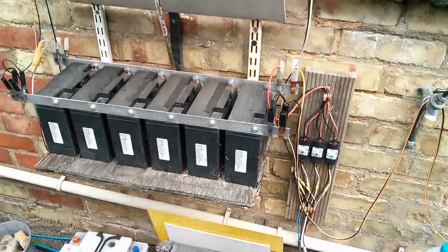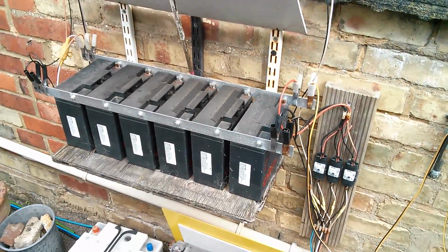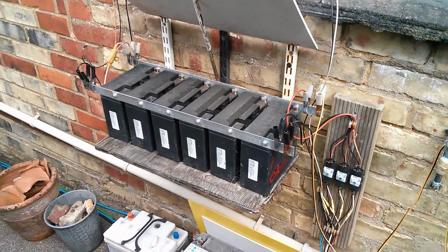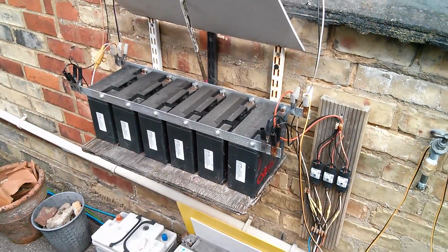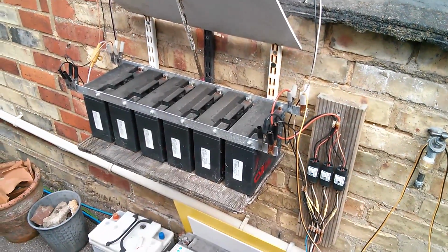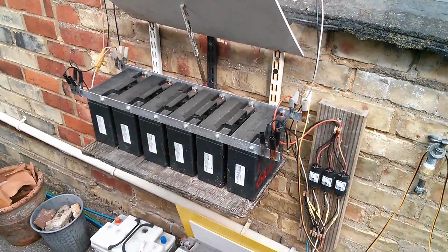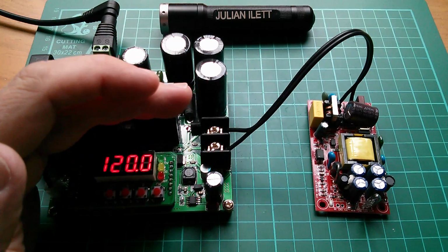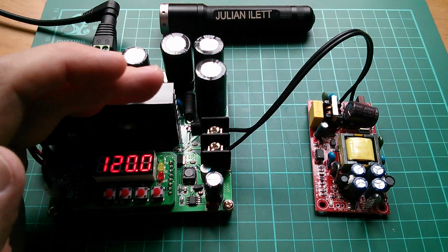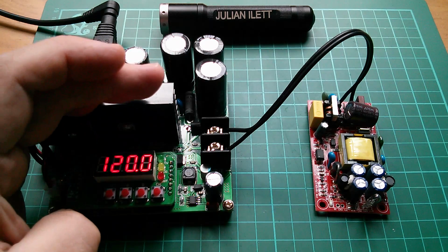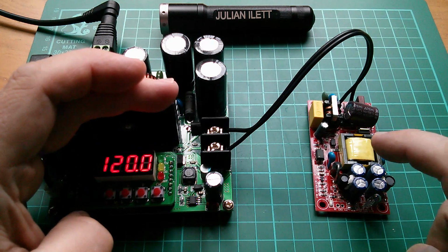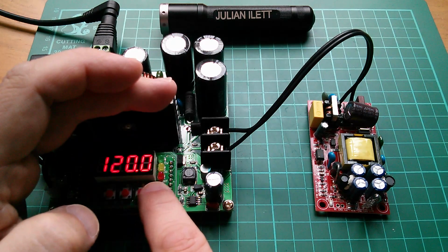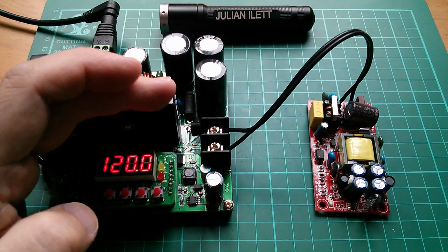And although this system still works, it is all getting a bit ropey now, and it'd be quite nice to have an alternative system using DC to DC converter technology, because I just love that technology, as an alternative to the existing low voltage 12 volt system. Now one problem is that this is the only boost converter I've got which can generate this high voltage, 120 volts. The other boost converters I've got several of, which only go up to 80 volts, may not be enough for this. So one thing I wanted to try was how low can I go in terms of DC voltage and have this unit still switch on.